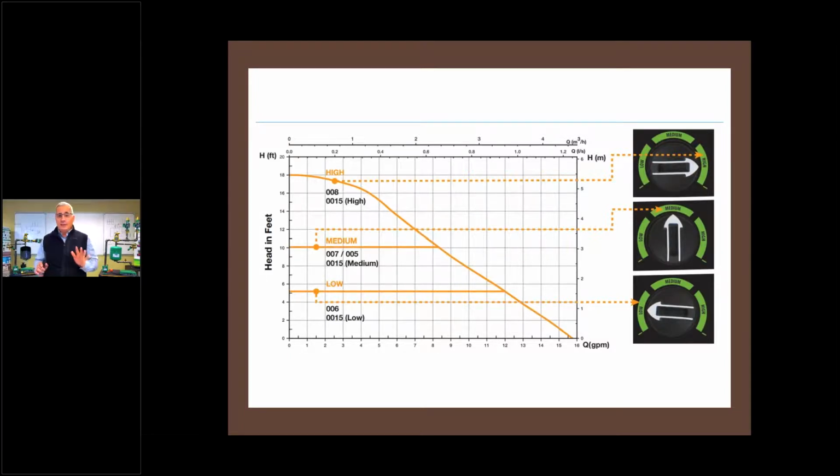Trust me, if you want to do it, I'm okay with that. We sell circulators, we're happy with that. But I could do this easily with just one circulator. We had 52,000 and change as our heat loss. That's 5.2 GPM.